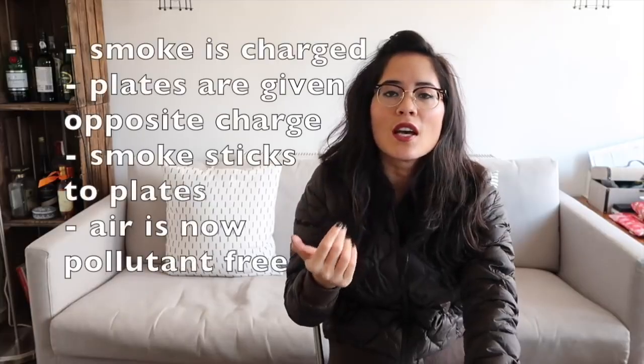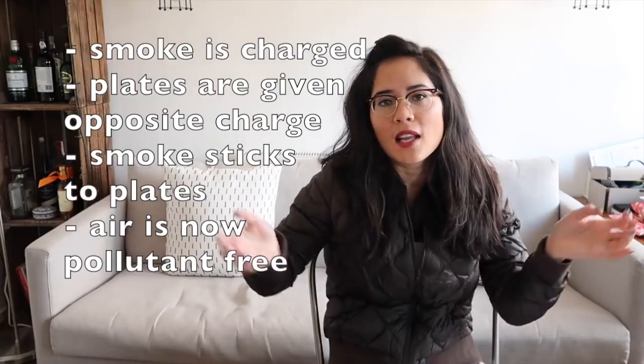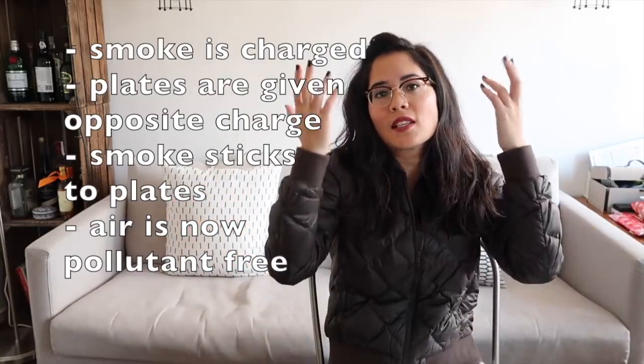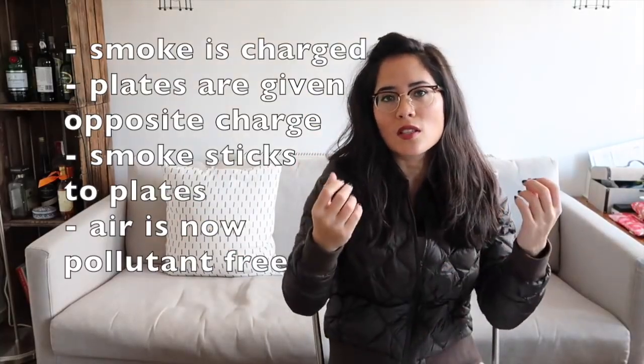One further use of static electricity is an electrostatic precipitator, and that's what they use in factories which produce a lot of polluting smoke full of soot and dust particles. So what happens is the smoke rises through this chimney, it's given a charge, and then there are some plates that sit at the top of the chimney that the smoke and everything has to pass through, and it's given the opposite charge, meaning that all the soot and dust particles stick to the plate, allowing just the clean air to basically escape through the top of the chimney. Then they knock those plates together occasionally, causing all that dust and sediment to fall down so it can be removed and safely disposed of.